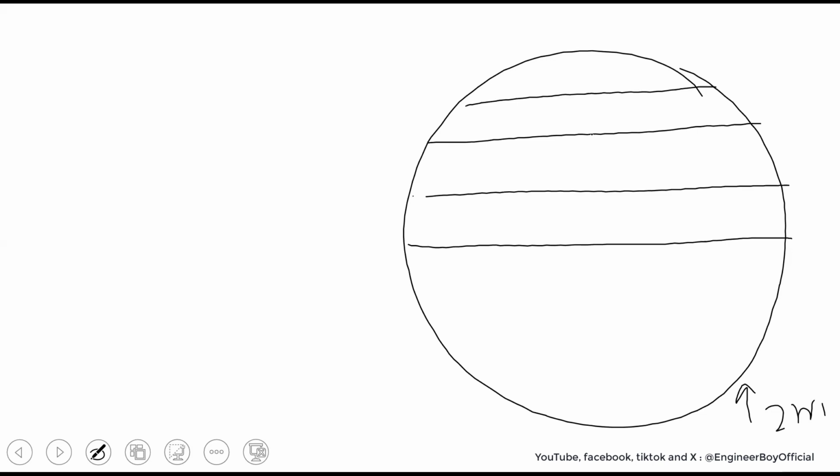There are bars like this. Let's say these are the main bars, 13 mm at 10 centimeters center to center. I'm going to call the length of the central bar L1. Let's say this is L2, then we have L3, L4, and so on. The length is decreasing. And the question is, when do we recognize the last bar length?